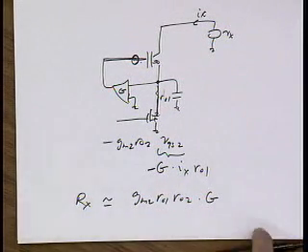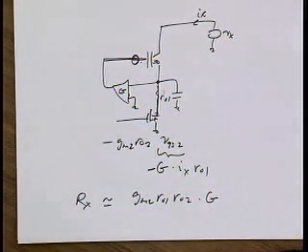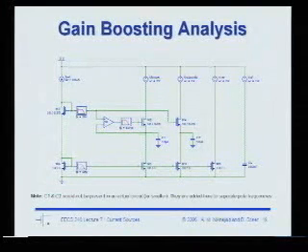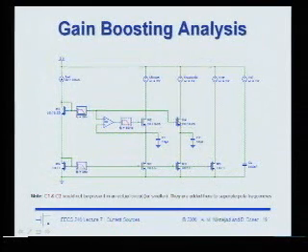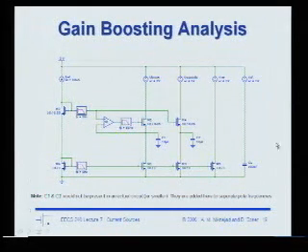All right, so here is a simple circuit that implements this idea. Let's switch the slide. Basically you have your regular device, M5. You have a regular cascode device with M3 and M4. And to make the frequency response more obvious, we've inserted a capacitor here on purpose, a 10 picofarad capacitor.